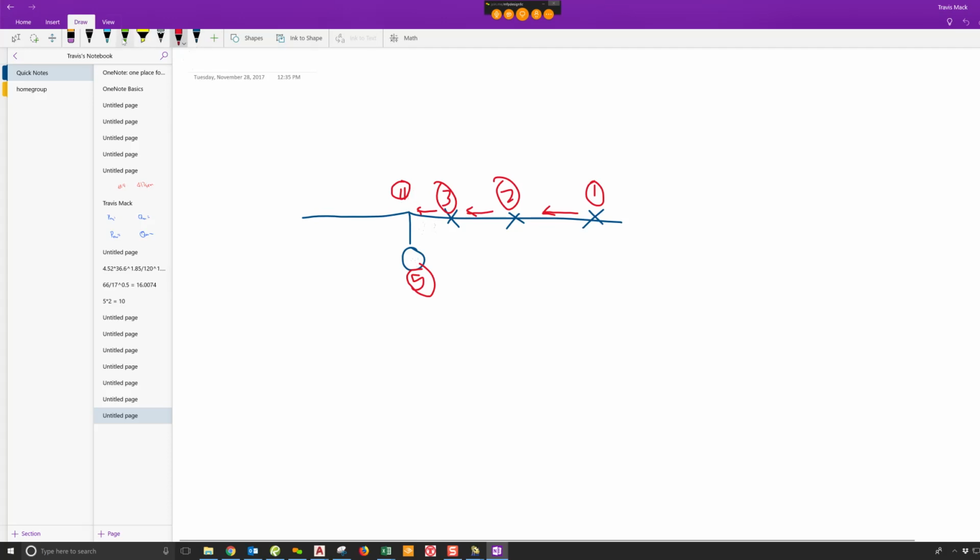The way that I was taught to do this, and it sounds really funny, but it gets you right every single time, is if you look at the direction of flow. Okay, so direction of flow is going this way. Say we're talking about the pipe from 4 to 3, or 3 to 4, however you want to look at it. If I picture sitting on this pipe in the direction of flow, and I look behind me, so I'm a little guy sitting here, and I'm looking this way, I turn around and go, what fitting did I just come through? I just came through a T. So the pipe from 3 to 4 is going to have 1 T on it.